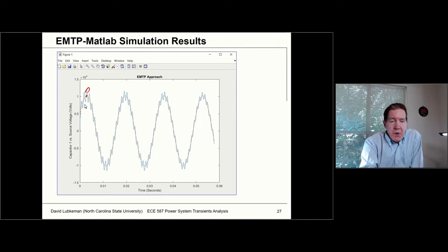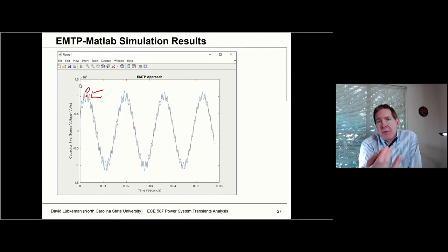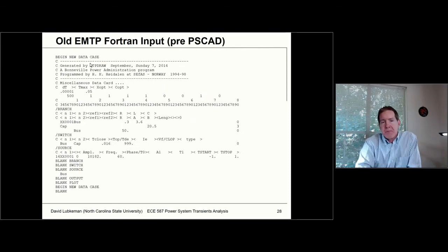All right. So this is what we're interested in looking at right here: what that overvoltage is going to be with respect to what it would be during normal situations. If that's going to cause a problem, then we could do different things to fix that. For example, we could put a surge suppressor there that's going to tend to clamp that higher voltage. So it's not really that much of an overvoltage in this particular case, but it is causing a little bit of an overvoltage.